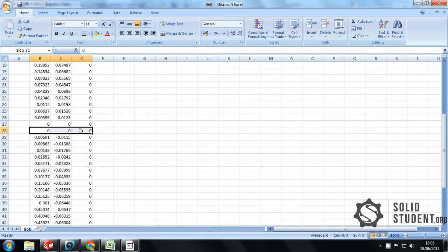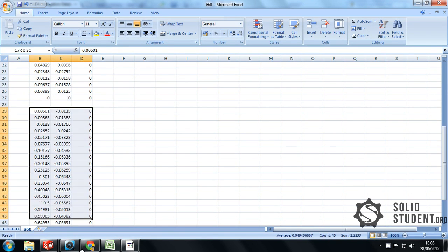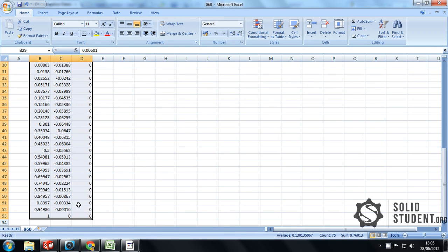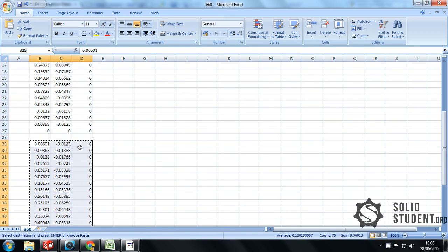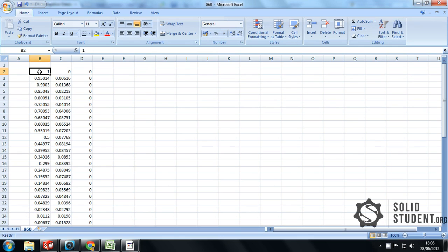Once that is done, I need to check if there are any repeated points, as Solidworks will regard the file as corrupt because it can't draw a smooth curve between 2 points that occupy the same position. Now that's done, a quick note on unit systems.